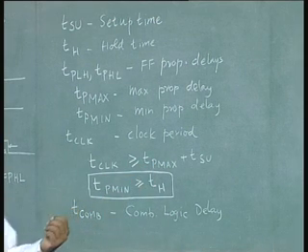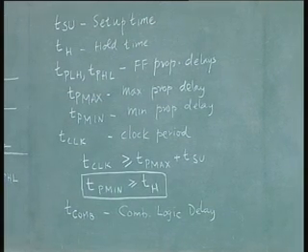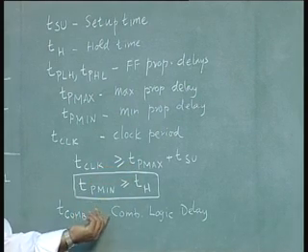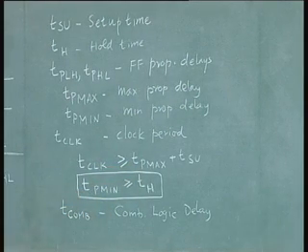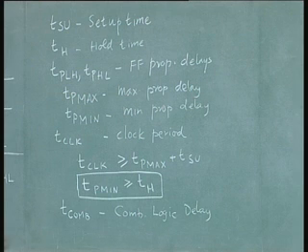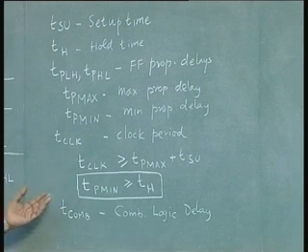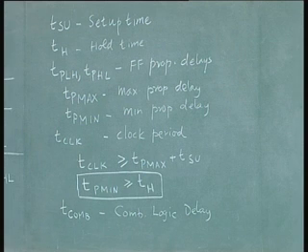So that means if there is going to be an additional time elapsed in propagating the output back to the input because of an extra combinational logic through which it has to pass, it need not be the same flip flop. The output of one flip flop can go to another flip flop through a combinational logic. So that is the time T comb. My equation will now get modified as T clock